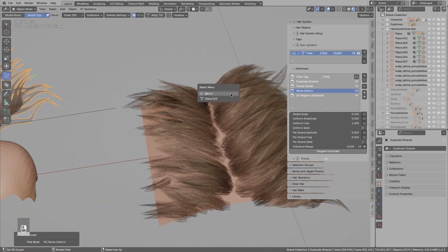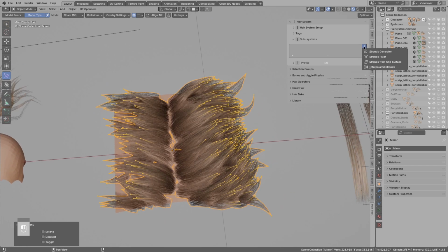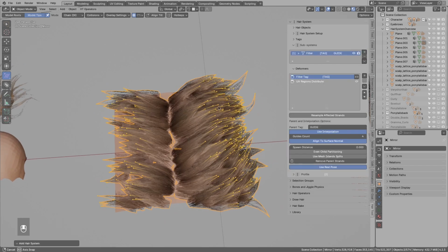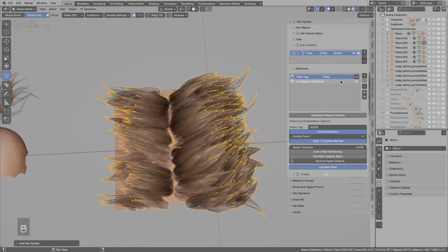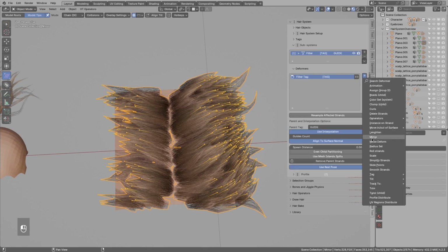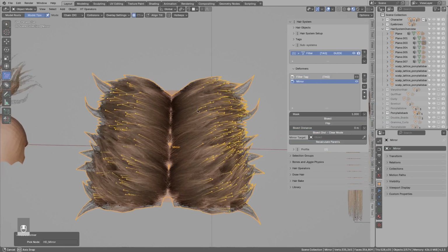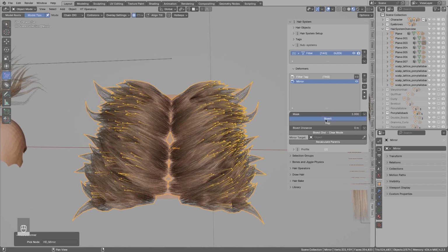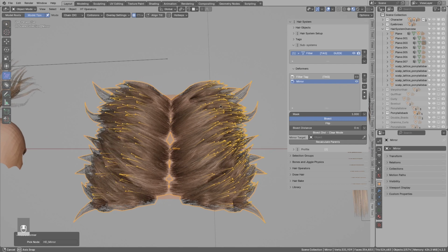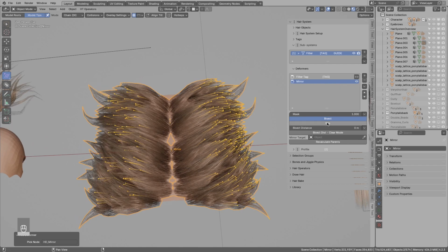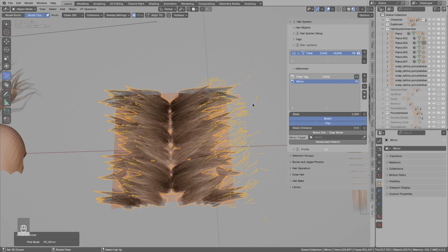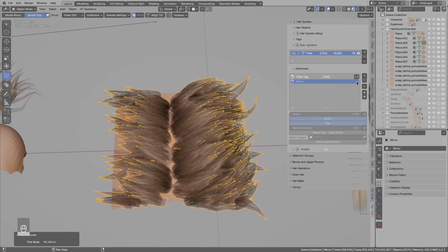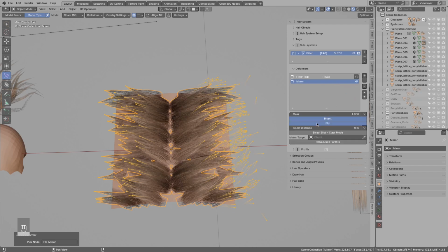In here I will show you mirror. So let's again add Strand Filter, so we do not generate new strands. And I will add the mirror. So quite simple. There is the bisect option, which will remove the strands from the left and duplicate the right side to the left. So without, with. If I flip the bisect effect, then the right side will be removed. So without mirror, with mirror.